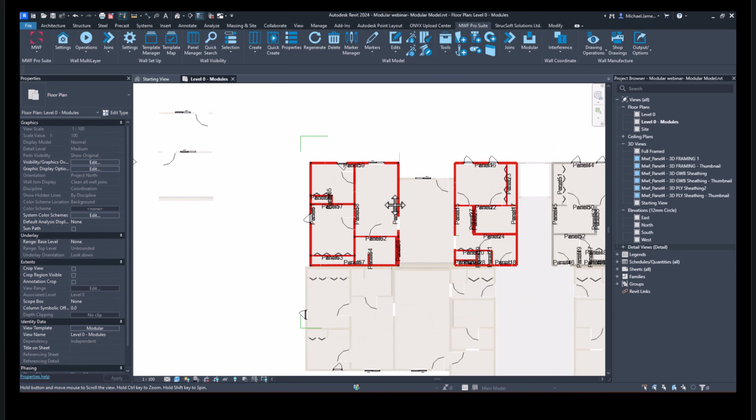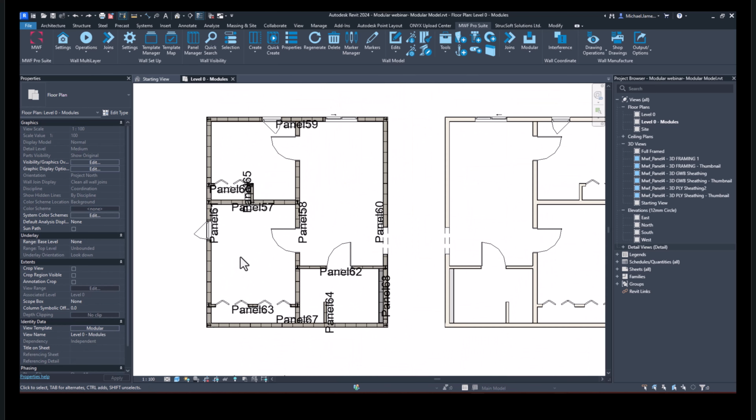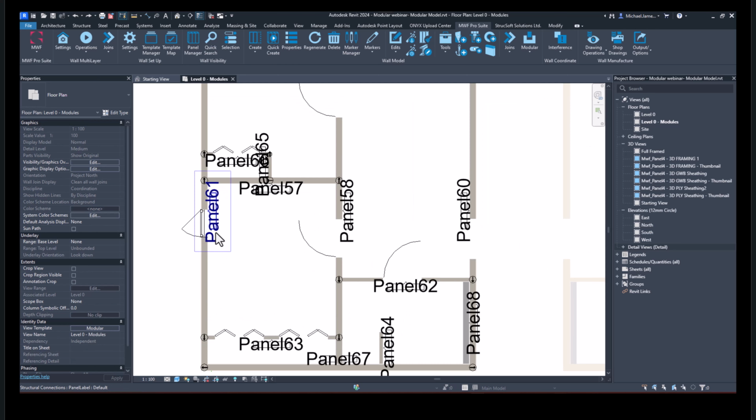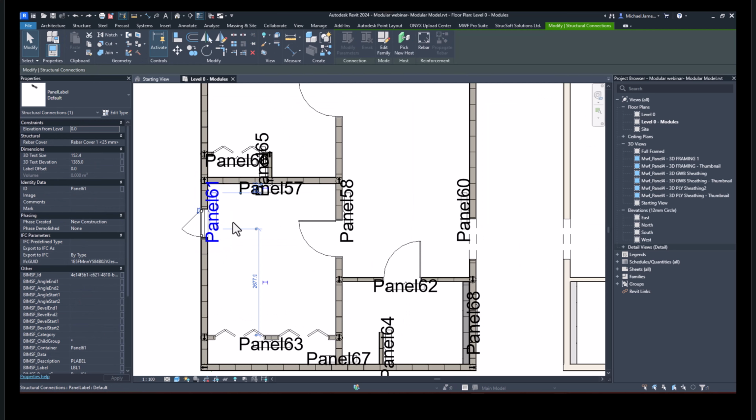So we have match properties on all identical groups. So let's imagine the change I want to make here is going to affect all of these existing groups. So now within the parent group, I'm going to make a change to one of the panels just so we can see that change reflected in the other panels. So what I'm going to do is pick panel 61 and go into the panel properties here.